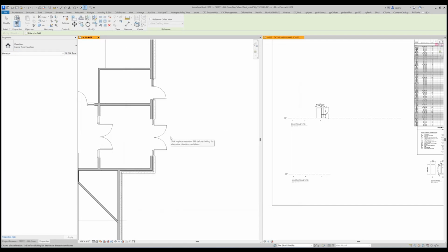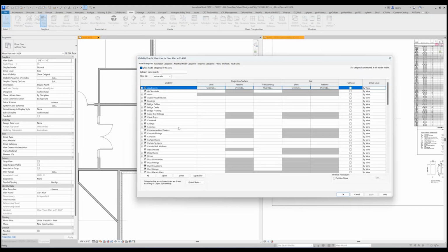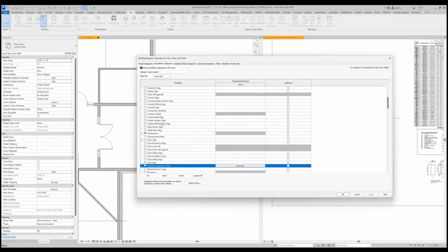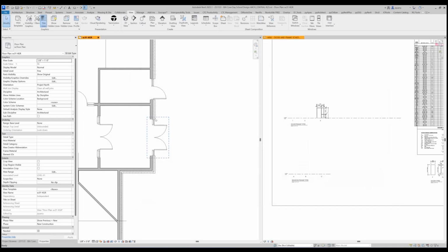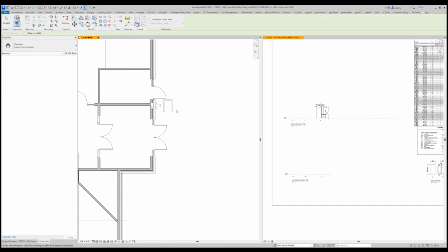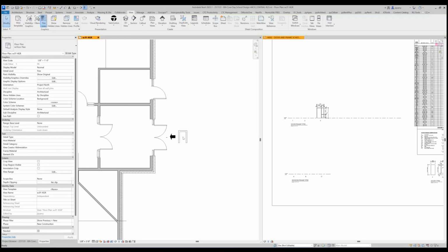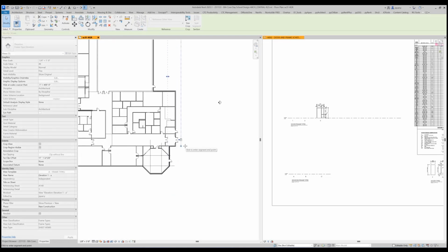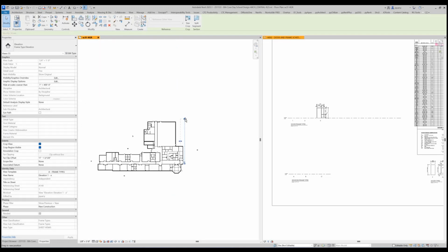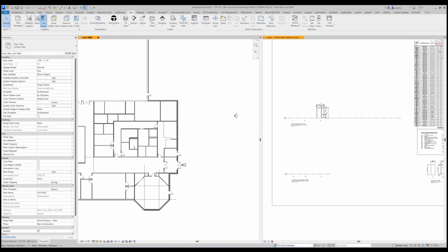All right. So I don't have elevations turned on here, so I need to go in here and turn on the elevations. Right, so view, elevation, frame type elevation. And as you go towards each, see how it automatically flips for you? That's what's nice about it. So I'm just going to place that guy right there. Then I'm going to select this guy and shrink this down to match the width of the door so it's not so doggone big.